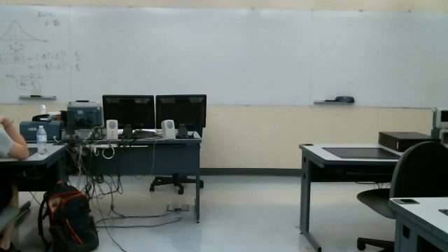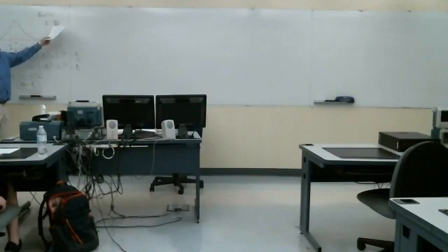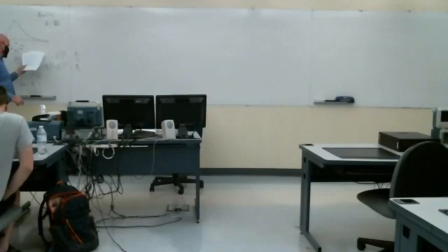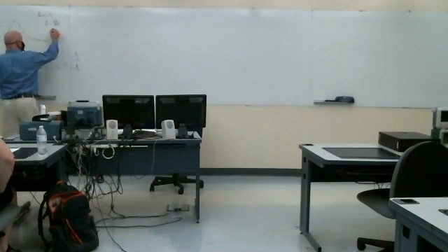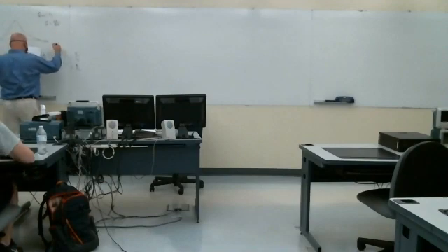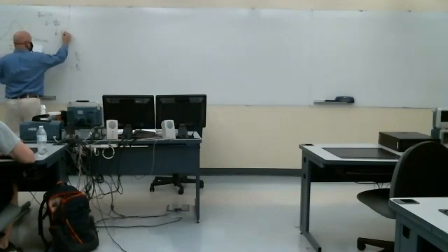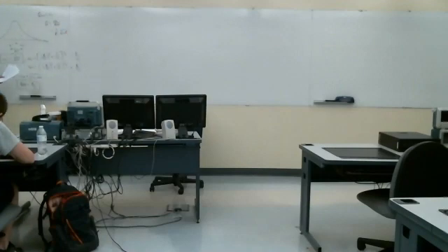Bandwidth is not always in radians per second. If we converted this to hertz, then we could express the bandwidth in hertz, but the quality would be the same. If we stick our formulas in, we can also work with the quality, and it's 1 over R times the square root of L over C.